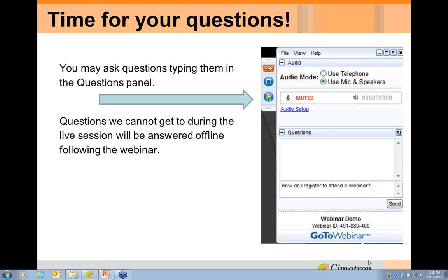Once you sort of move down that list, you really should stay there. And I think it's kind of obvious. If you're taking a change and comparing it to the work file, it should always be up to date. But if you're moving it down into the bottom of an organized tree, of a history, it's a bad idea then to say, well, for the next one, let's shove it in at the top, because it's not going to recognize that new geometry until the end. So you can mix and match, but if you go in one direction, you really should stay with the last option you picked.